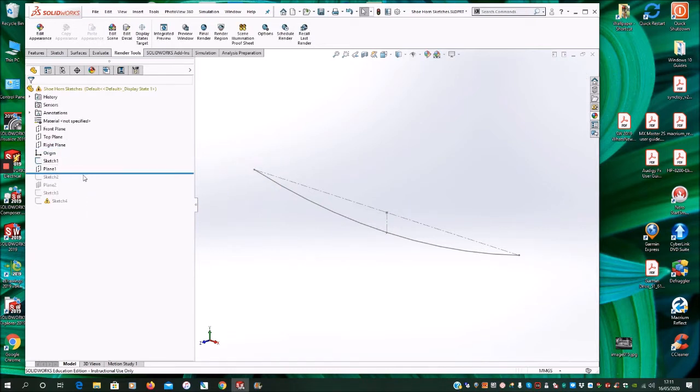On that plane we position that sketch, and again that sketch is just measured directly from the shoehorn. I've measured the width and the approximate radius and positioned this point in the center and made these 2 points horizontal, and then I did exactly the same at the other end. I did a new plane and another sketch at that end. Ignore this one for now.